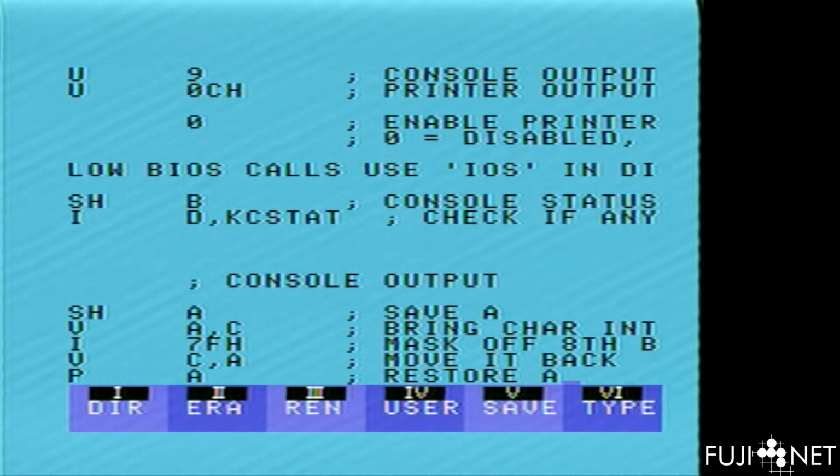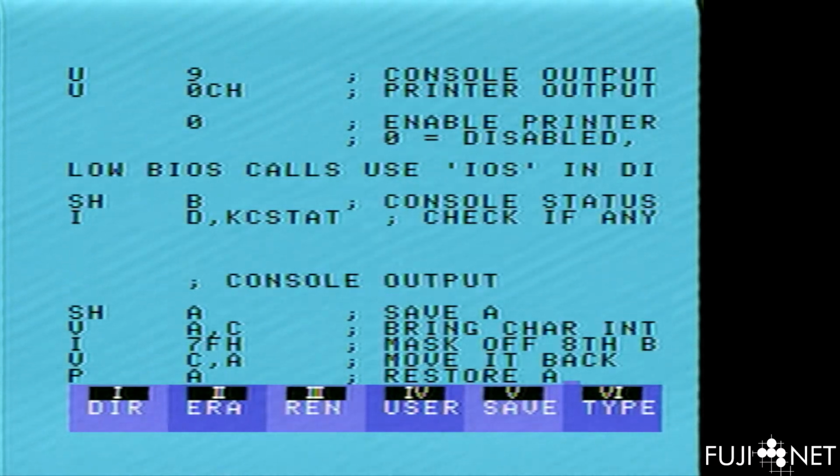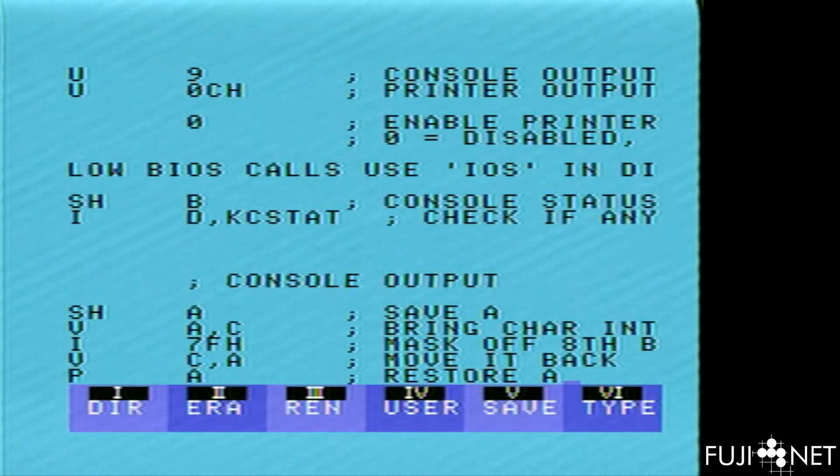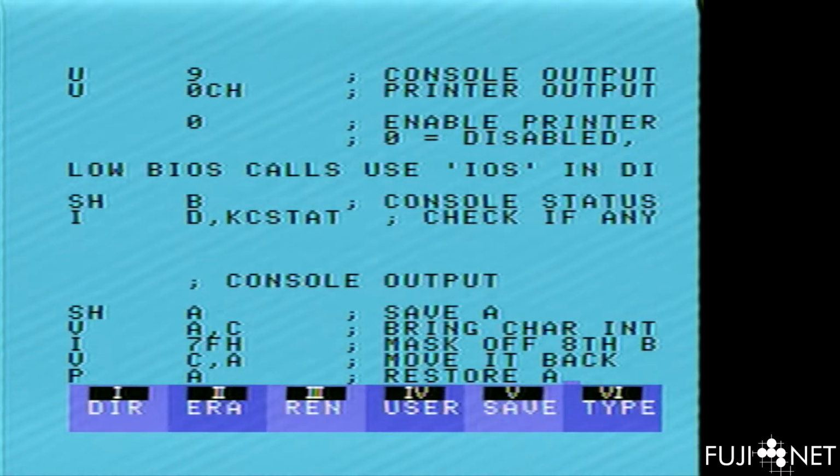If we use any registers for quick temporary processing, we need to remember to push things onto the stack, do what we need to do, and then take what we have off the stack so that everything is still nice and clean and the rest of the program can run as intended.